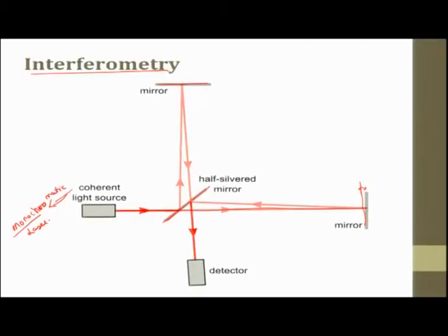So, there is a phase difference between these reflections, maybe A1 and A2, and that difference is pushed into the detector. In this detector the fringe patterns are counted and you report it as linear displacement. This is a typical interferometry principle.